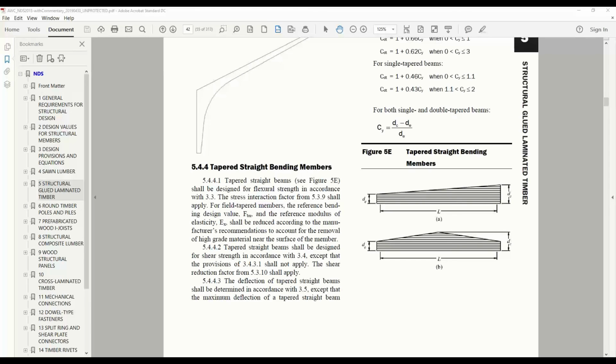Yeah, and my understanding is that that's typically where we see it most of the time. When we say proof loading, it is kind of a load that proves that it can sustain the stress. From a wood science standpoint, like Liz said, the finger joints are typically the critical location. So that's typically where we see the proof load required the most.